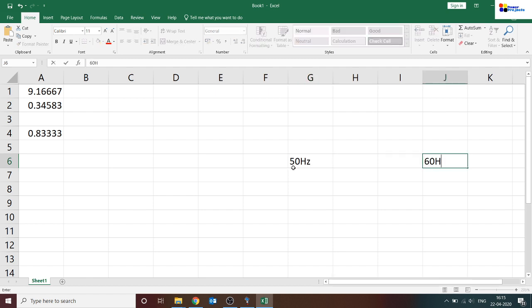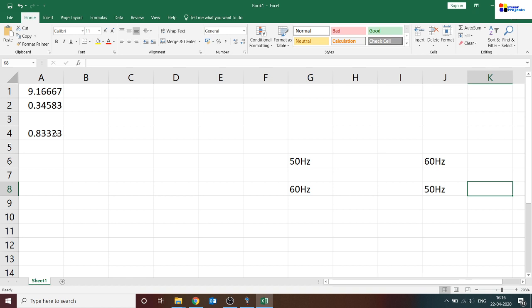I can use it with the same capacity, but there will be drawbacks of increased real power loss, increased reactive power loss, increased voltage drop, and an advantage of reduction in the short circuit current on the low voltage side. But if I am trying to use a transformer designed at 60 hertz at 50 hertz, you cannot use it. If you want to use it, you have to reduce the voltage to 83.33% on both sides and then you can utilize it.